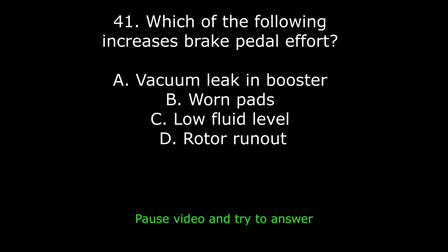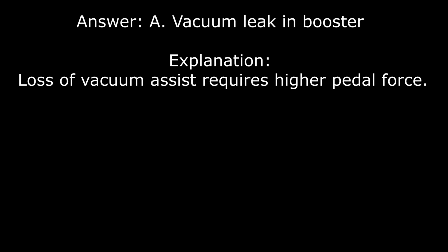41. Which of the following increases brake pedal effort? A. Vacuum leak in booster. B. Worn pads. C. Low fluid level. D. Rotor runout. Answer A. Vacuum leak in booster. Explanation: loss of vacuum assist requires higher pedal force.